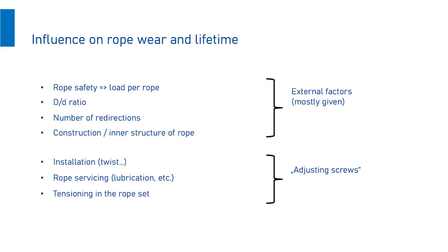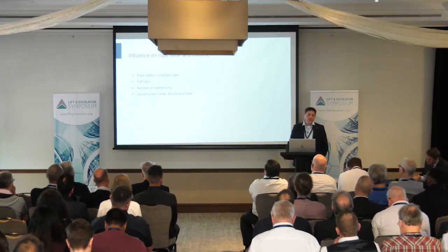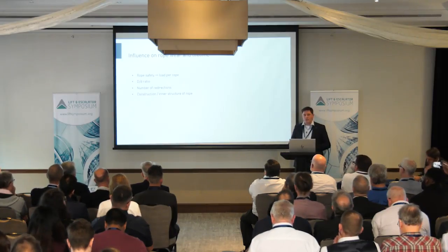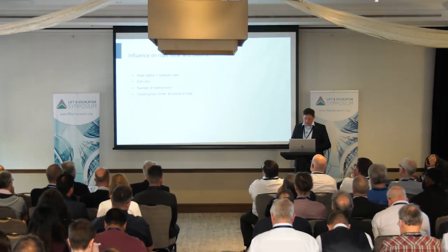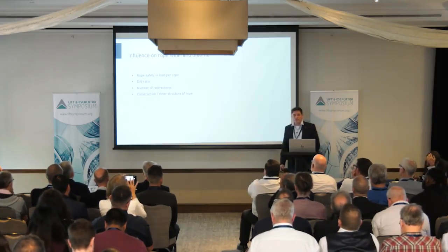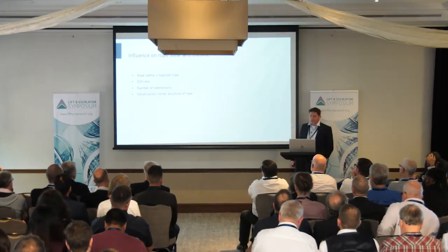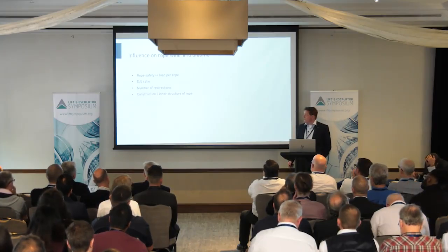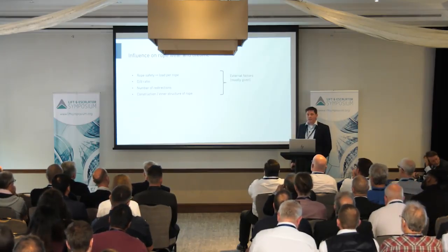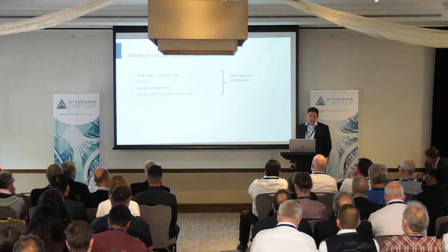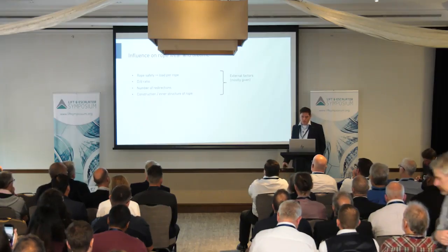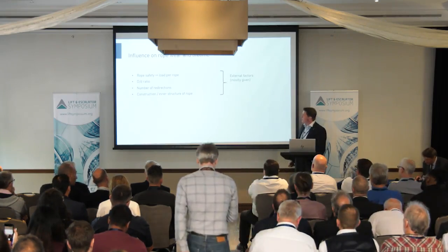First of all, I would like to talk about the things which are causing wear in suspension means. So there are some topics. Rope safety, you all know that, how much load you have in the single ropes. It is the D-to-d ratio, the ratio between traction sheave and rope diameter, the number of redirections, the construction of the ropes, but all these points are external factors. They are given as soon as the elevator is installed. So during service, during maintenance, you cannot take care of that.